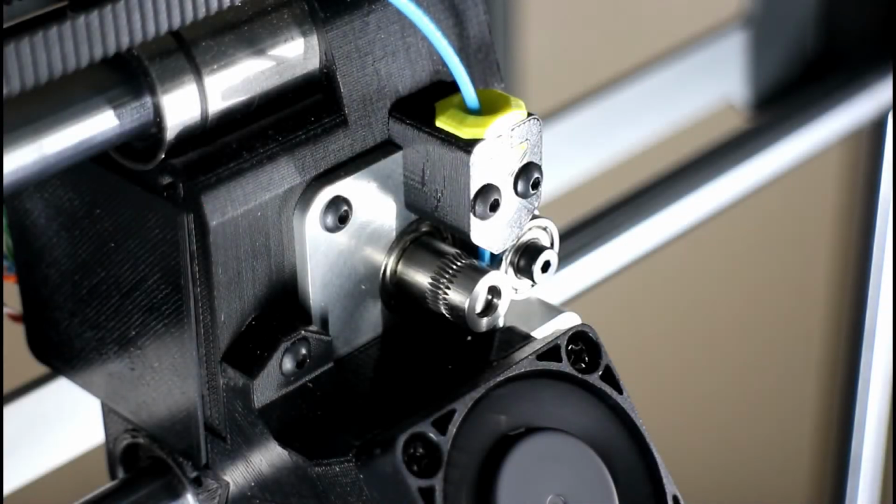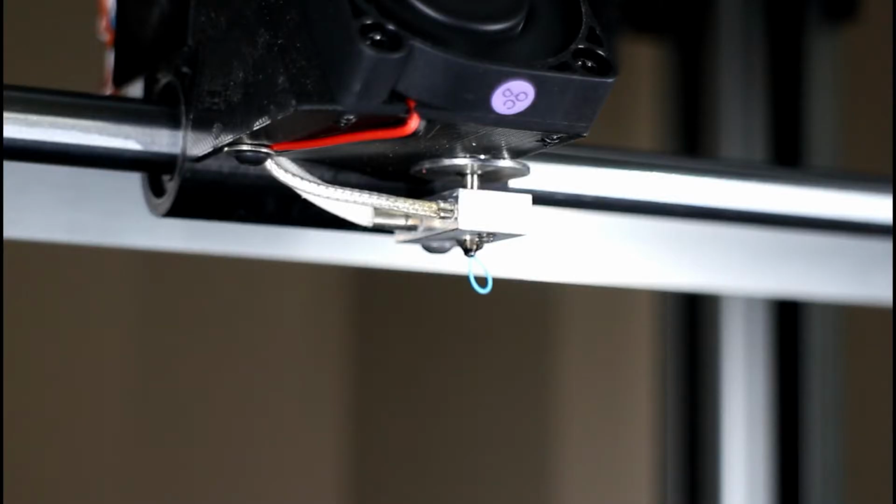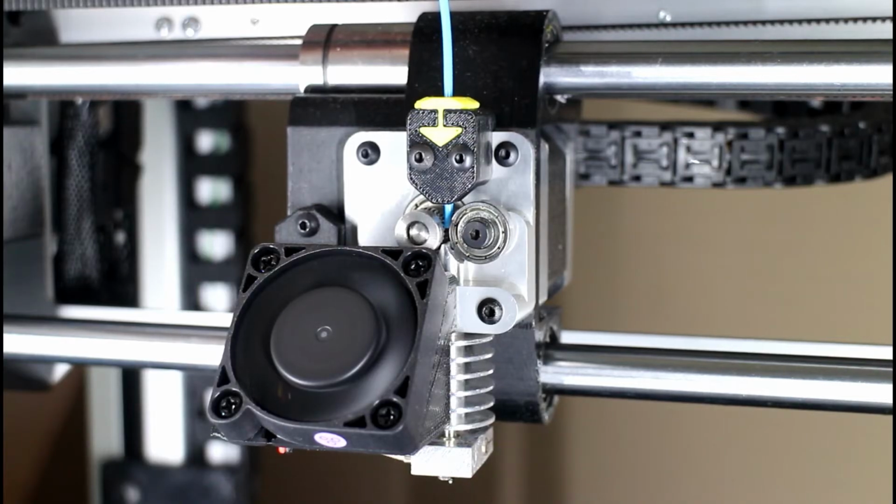On the SX, filament is driven down into the nozzle, where it is melted and continues through onto the heated bed to build a printed part. The nozzle, of course, gets extremely hot, so be very careful not to burn yourself on the heated nozzle. The fan in front of the nozzle works to hold a constant temperature within the nozzle itself, so it is important that the fan is never obstructed and remains running.